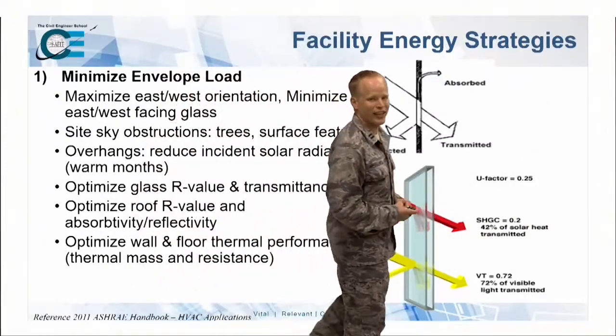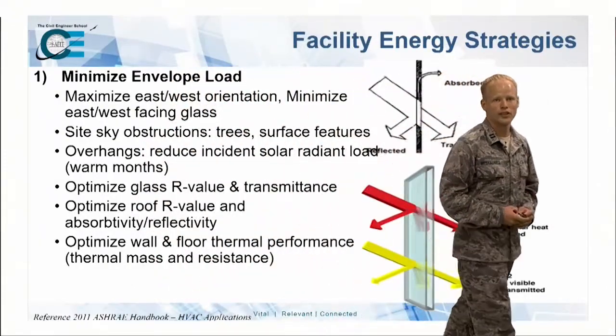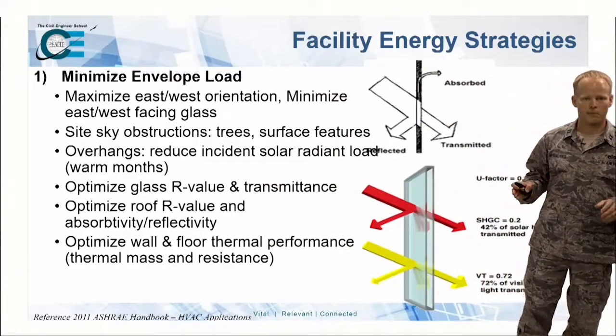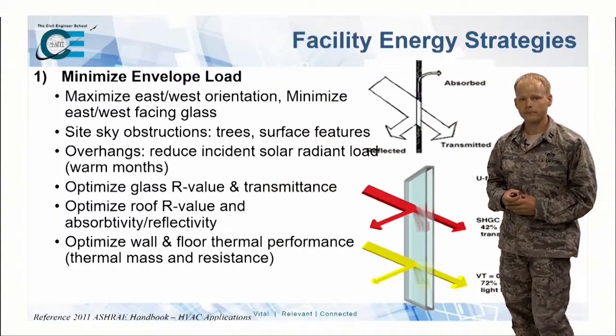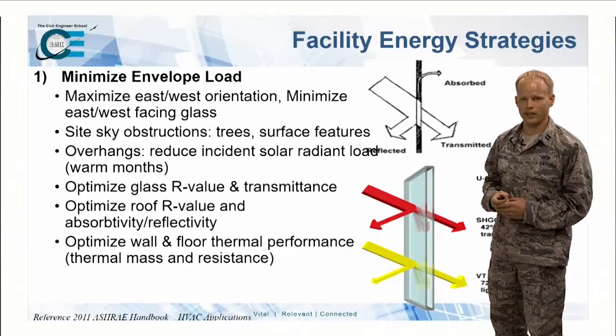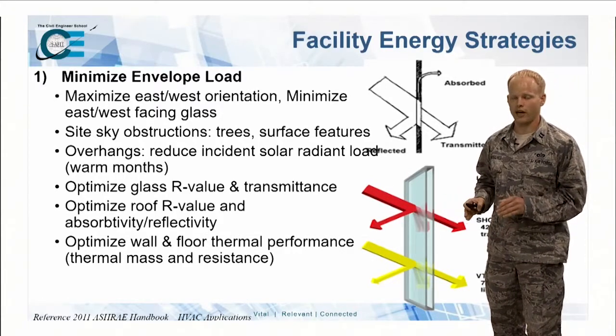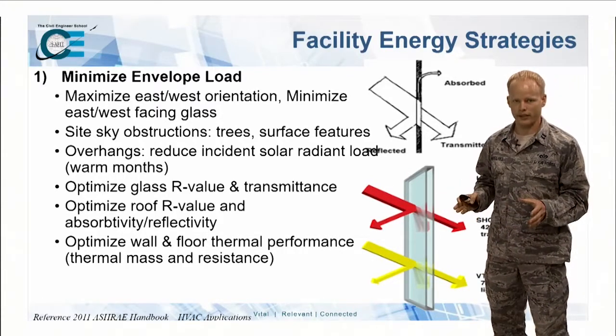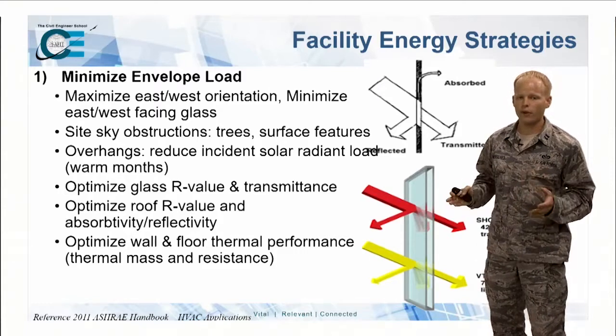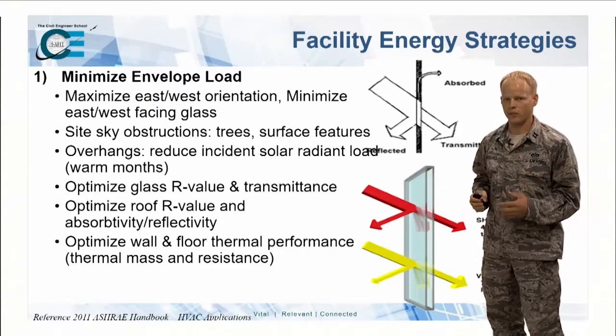So, talking about glazing and reflective coatings, let's first start off by minimizing your envelope load. Maximize your orientation. I know Captain Tomaszewski was talking about how you site your building and how you are going to orient it. That will affect how much energy your building uses.